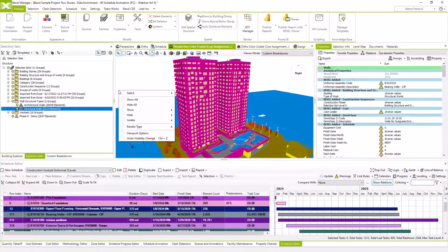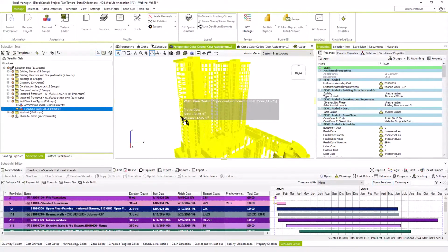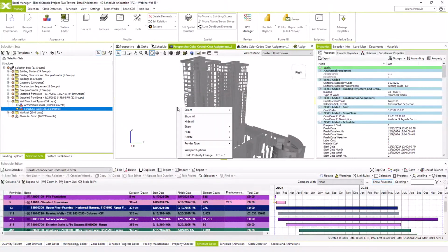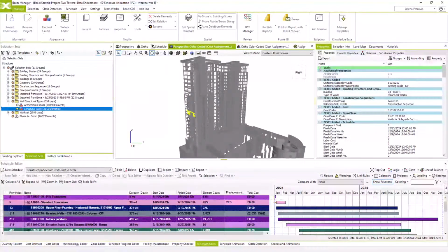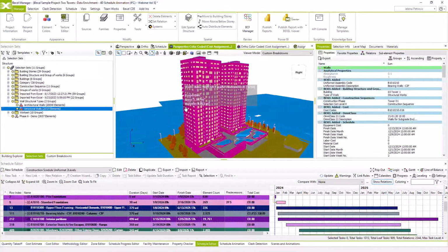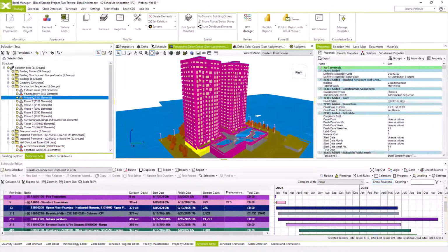And finally, I'm going to create only one smart selection set, which will use the construction phase property we have enriched our BIM model with using scripts, even though we already have this selection set here, the one I have created manually. Someone would say I'm talking about the construction phases property mostly and I'm going in a circle. But still I find explaining options on a simple example useful, so they can be used with any other property, not just construction phase.